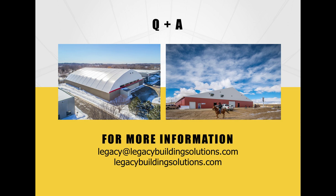Okay. What type of insulation values do these structures provide for energy code compliance? So that may vary a little bit from manufacturer to manufacturer. Here at Legacy, we have systems to allow us to insulate up to R30 and beyond, and allow us to do the appropriate energy code compliance evaluation to ensure that the structure meets that.